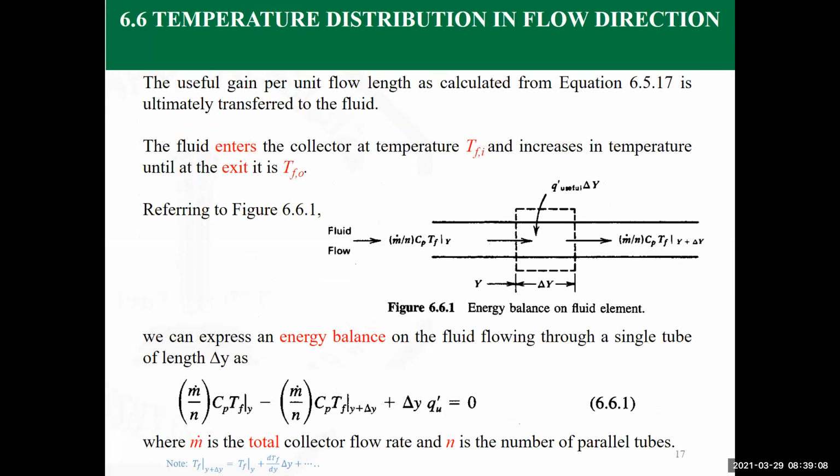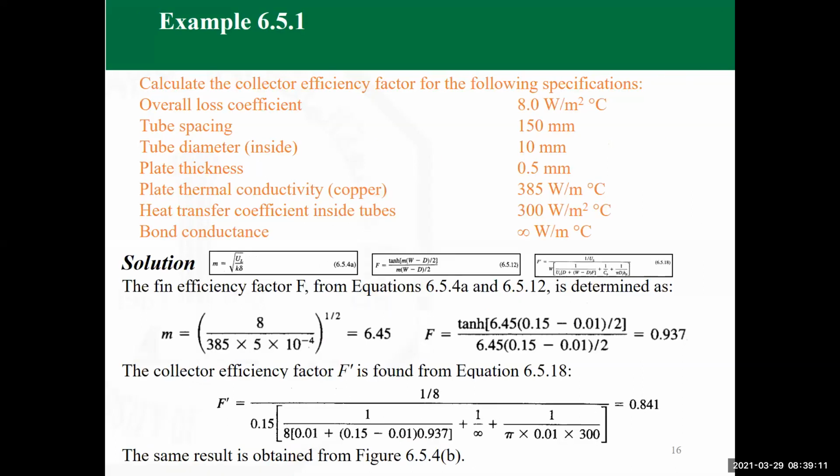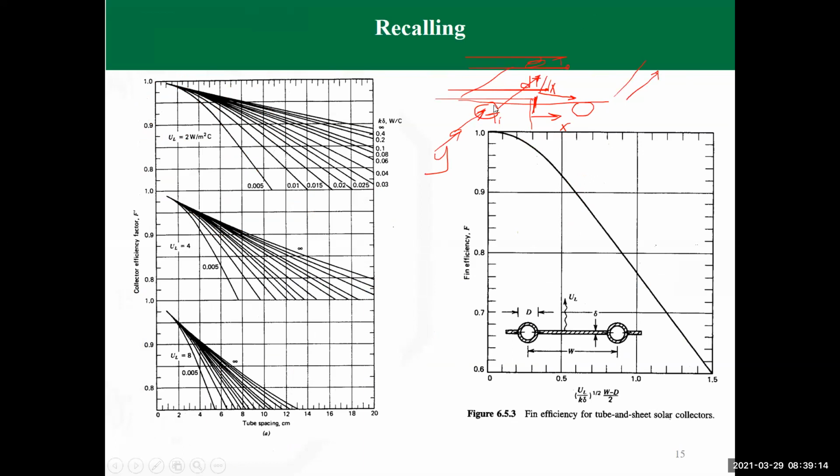What we need to look at today is the flow direction, which is, again, the flow in the pipe. As you can see here, it is entering with a temperature T inlet, and this temperature should increase as we are moving along the pipe. The heat transfer to the fluid is occurring by convection heat transfer. And who would remember convection heat transfer is controlled by which law? Anybody remembers? For convection heat transfer calculation? Newton's law of cooling. Yes, Newton's law of cooling, this is correct.